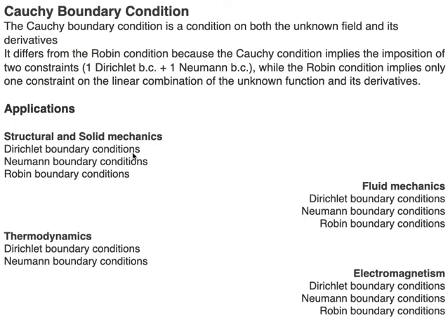For instance, frame structures are based on beam theory and the related finite elements have 6 degrees of freedom, that is 3 displacements plus 3 rotations in 3D space. For 2D problems, each node of the boundary has 3 degrees of freedom on which Dirichlet boundary conditions can be applied: the two displacements, ux and uy, and one rotation, which we can call omega.